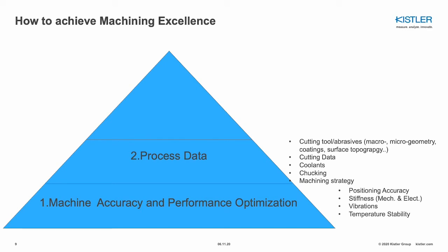And so we have done the first step, the second step, but remember that you have a machine and you have tools that are wearing out during the process. So you would like to make, or you need to make, compensations of such wear and be able to monitor and detect that. And at the end, when you do that monitoring and detection and control, then we are talking about intelligent machining.